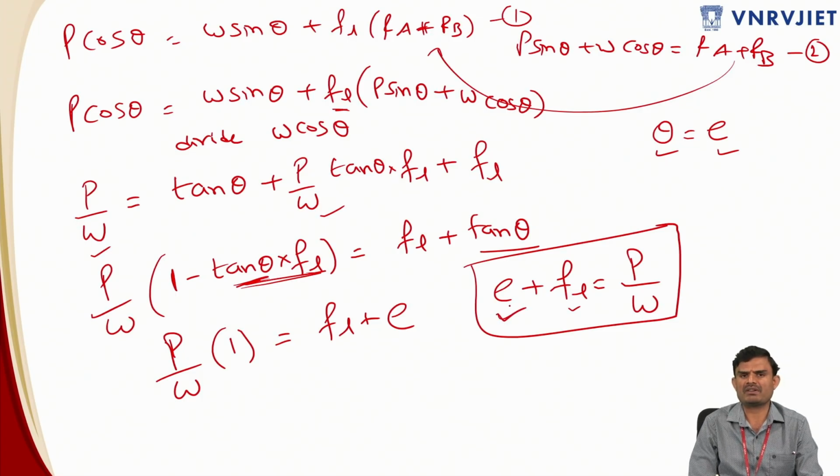That is the main purpose of introducing the superelevation, and at the same time you also have another parameter. You can take another advantage of the road, which is the lateral coefficient of friction, in reducing the impact of centrifugal forces. Either you can provide any of them or you can provide only one of them, such that you can reduce the impact of centrifugal force and keep the vehicle stable while traversing the horizontal curve.